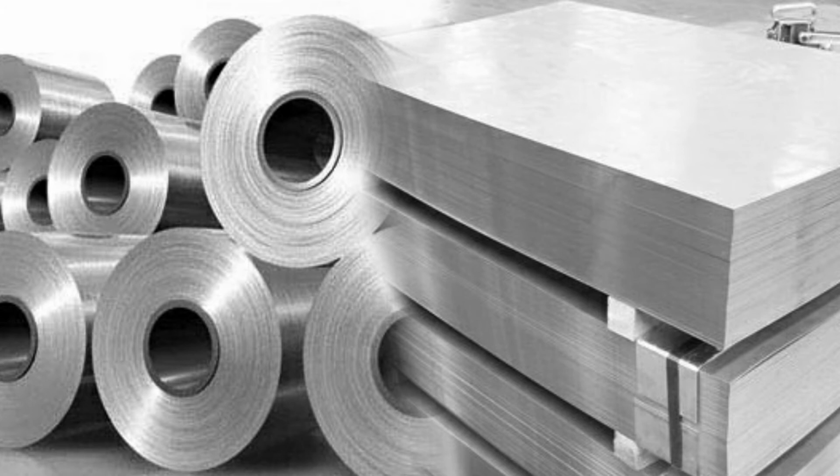So let's move on to plate and sheet steel. Both of these are pretty much the same. Plate is generally thought of as coming in fractional or millimeter thicknesses, and sheet steel comes in gauge thicknesses. Gauges are backwards, just like electrical wire is. The lower the number, the thicker the wire is. Same thing with sheet steel. So 7-gauge sheet is much thicker than 16 gauge. In fact, 7 gauge is 0.1793 inches thick and 16 gauge is 0.0598.